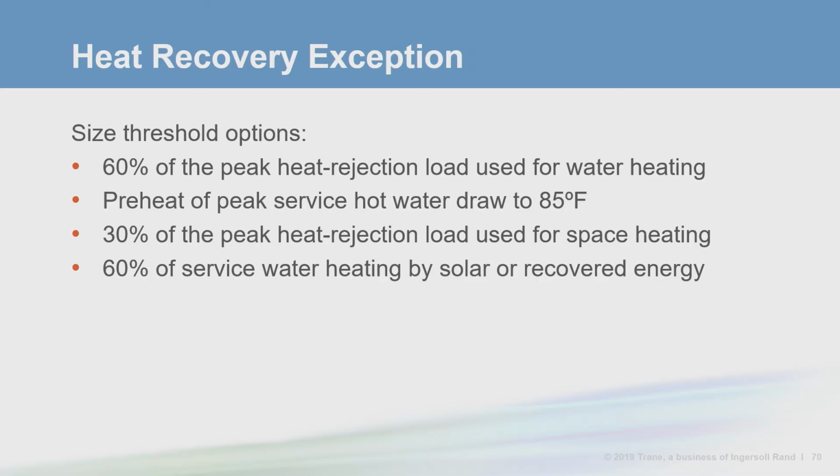Heat pump and heat recovery chillers could be used to qualify for this exception. Keep in mind that the heat rejection load is approximately 25% more than the cooling load due to compressor heat.